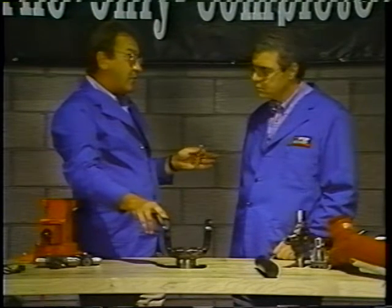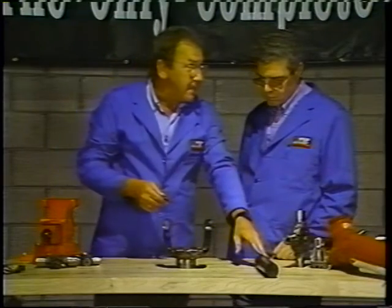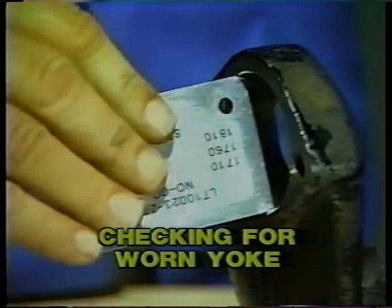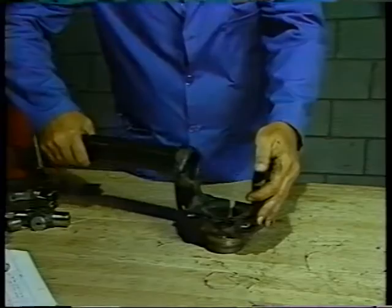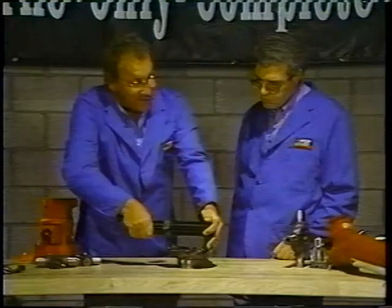Now, you can check for a bent yoke with a Spicer go, no-go gauge and the alignment bar. If the gauge fits into the yoke at any point, the hole is worn and the yoke should be replaced. The alignment bar should be able to pass easily through both cross holes if they are aligned correctly.